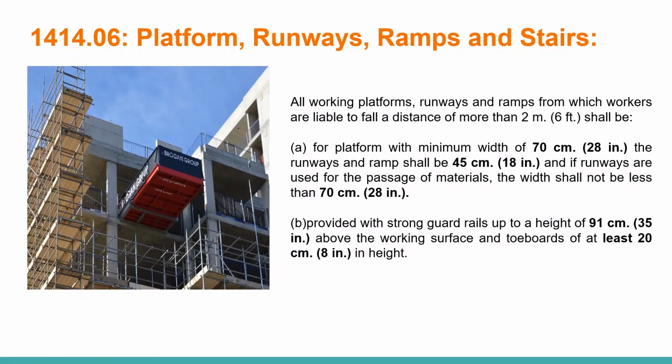Platforms, runways, ramps, and stairs. This is important in construction sites, and all working platforms, runways, and ramps from which workers are liable to fall a distance of more than 2 meters shall be 45 centimeters for platforms with a minimum width of 70 centimeters.